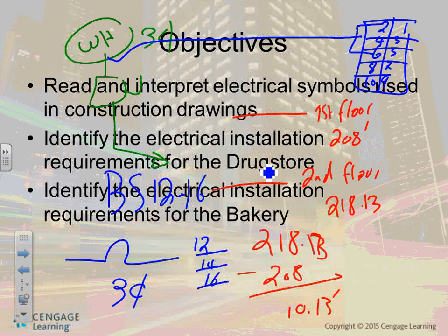Okay, you see the amps? What does the amp stand for? Meter. So how many meters do we have? 6. 1, 2, 3, 4, 5, 6 meters. Can you see them? So we go through the meter, and then they have a fuse disconnect. If you look at the beauty salon, the upper left, it says 200 amp. The first 200 amp is for the disconnect. The second 200 amp is for the fuse. 200 amp disconnect, 200 amp fuse, going to the beauty salon.